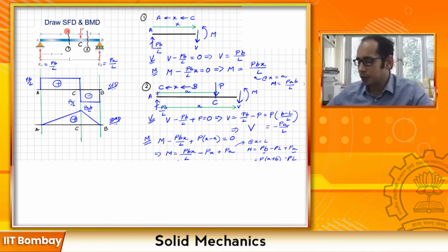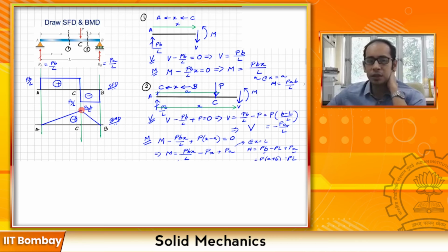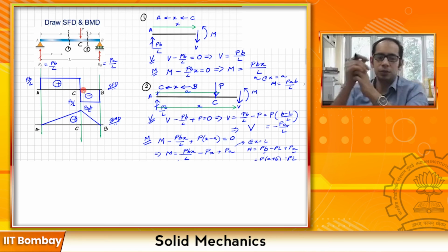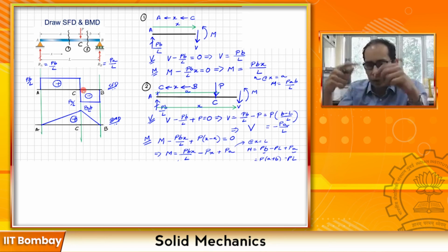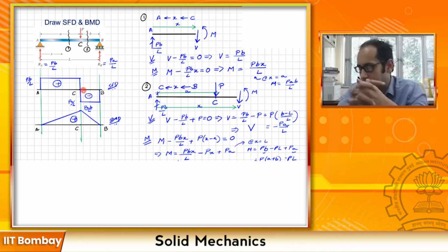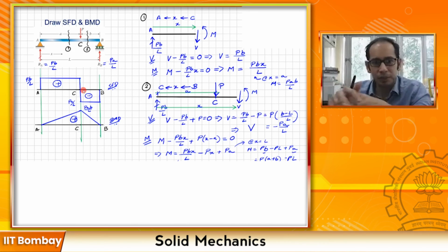Now, just a few key takeaways from here: can you guess the point where the bending moment becomes maximum? As you can tell, the bending moment becomes maximum over here. And how does the shear translate over there? See, at that particular point the shear goes from positive to negative, so there is a transition. So we will discuss more on these intuitive correlations or the links between the shear force diagram and the bending moment diagram later when we learn some of the relationships between these types of forces. But I hope that this first simple example is clear.